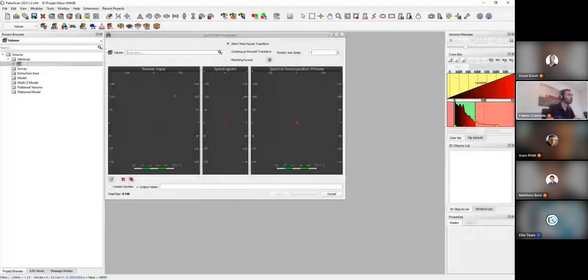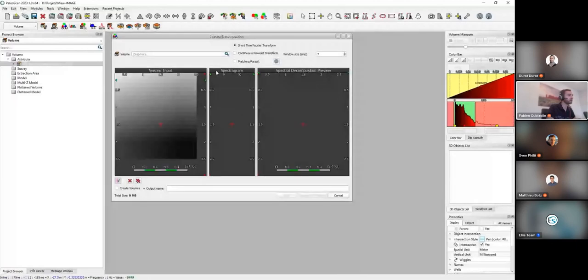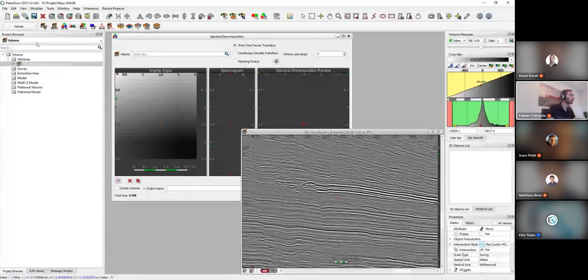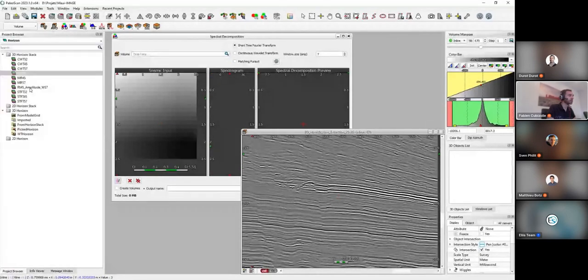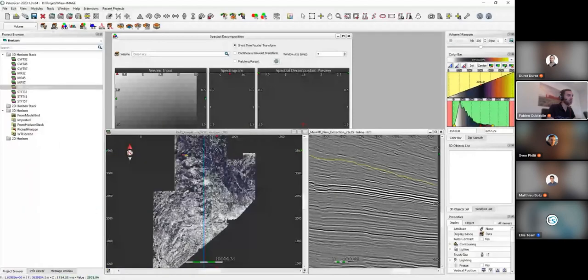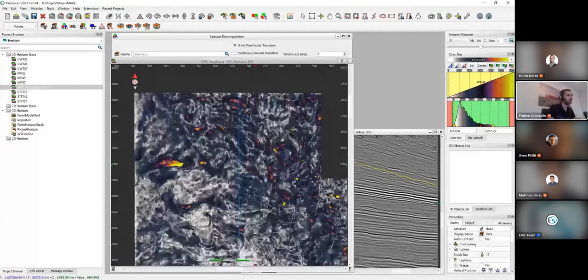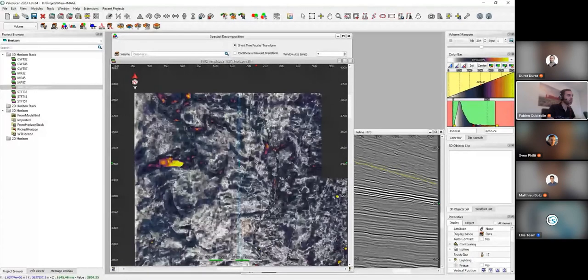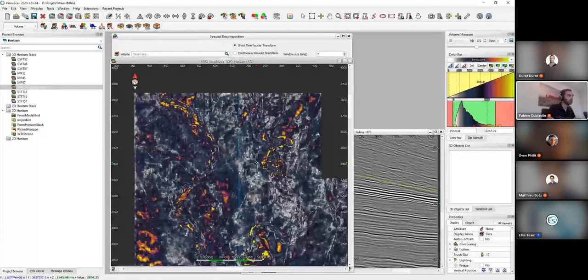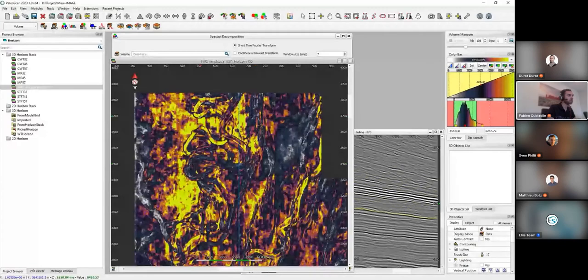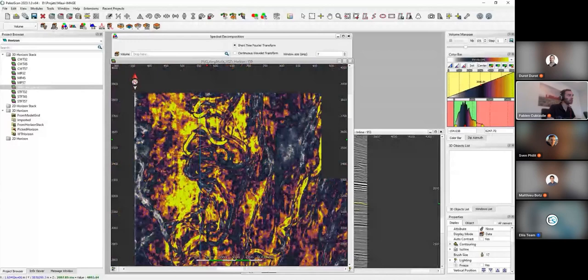For this example, I will use my data, which is a great seismic data with a lot of geological features, such as channels. I can display here a horizon stack with RMS amplitudes along this seismic. This horizon stack has been created thanks to the model grid of PaleoScan. Then we will focus on a specific channel, which is this one. We'll try to highlight this channel thanks to the spectral decomposition using matching pursuit.